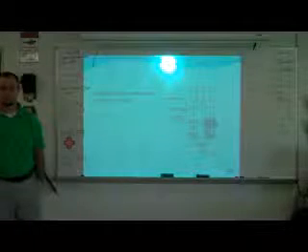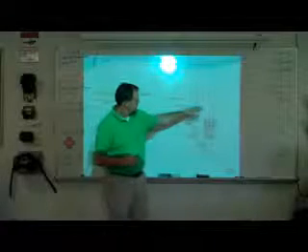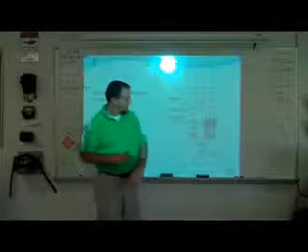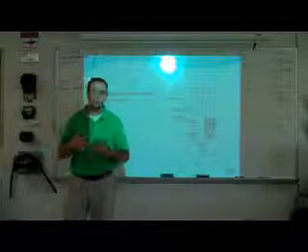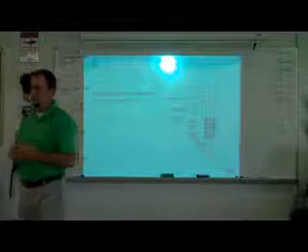All grounded conductors are not always neutrals. You don't always have a neutral. Most systems, yes. Not all systems. What it's showing here: here's your transformer. You have your three phases. You have three hot phases. You have 480 volts between each one. They are hot. When you're talking about a three-phase system, you don't have a neutral. You don't always have a neutral. Just remember that. A white wire is not always a neutral.